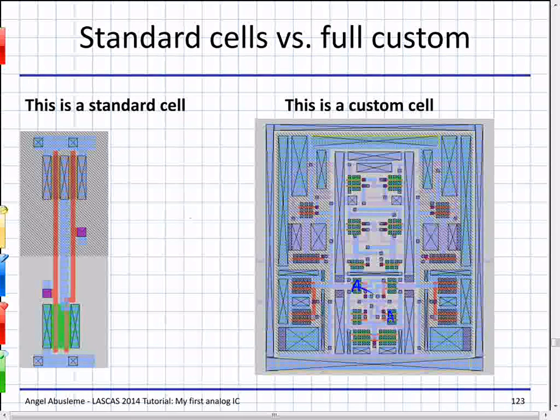So here we see cross-quadding. These transistors are cross-quadded. They share the same centroid. Same for these two here. And there are some other transistors here that are fully made by hand. This circuit is a comparator. This is a voltage comparator with a latch. It's a latch comparator.